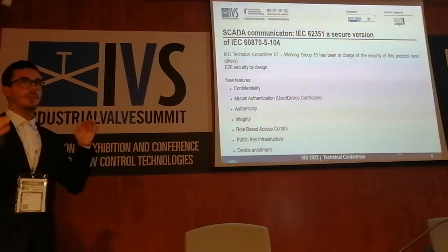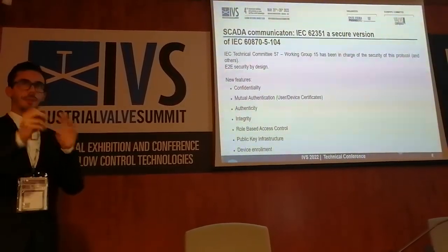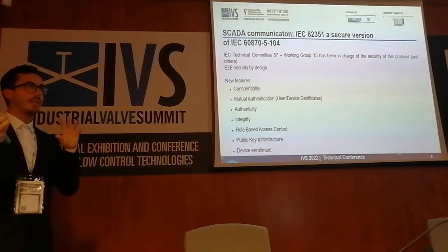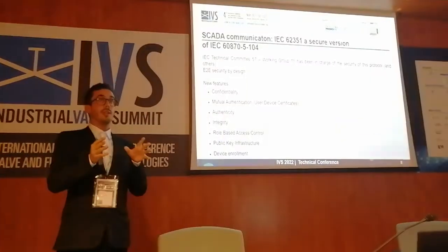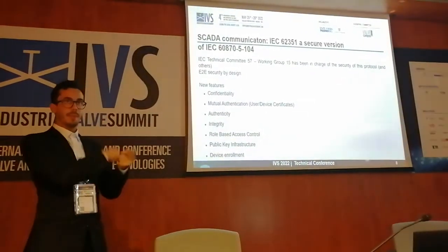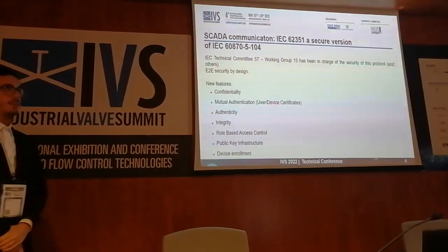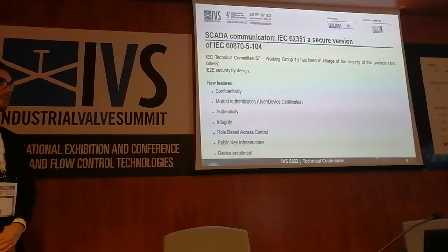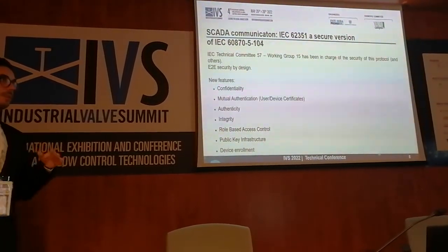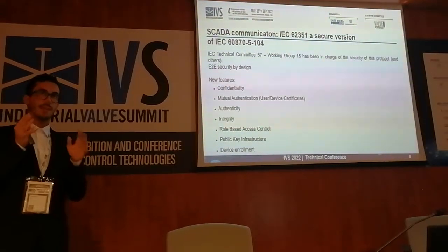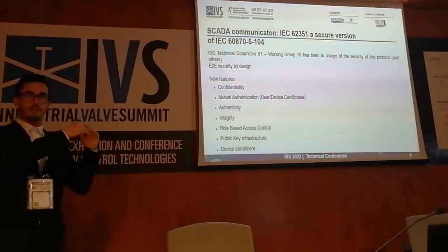Part 3 uses TLS communication and mutual authentication of the devices involved in the communication, to understand if the device that is connected is really the device that you want to connect to, and vice versa. And it's possible to authenticate each command. So for example, if an operator is sending a command, it uses authentication to recognize if the person sending the command is really that person and is authorized with role-based access control.